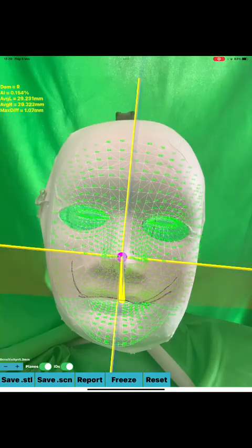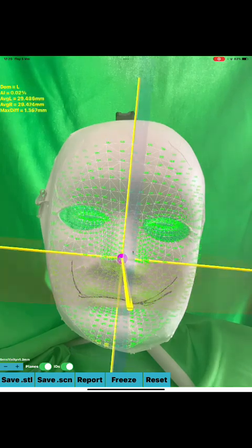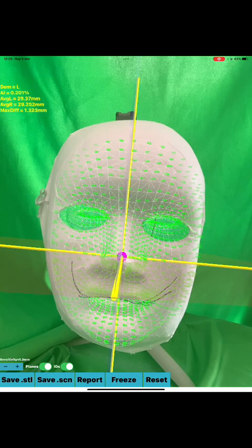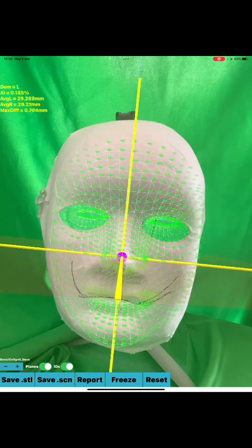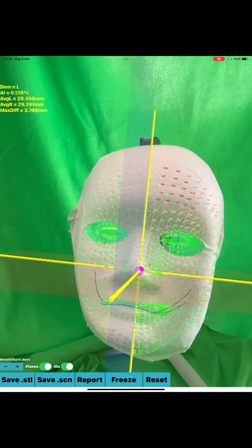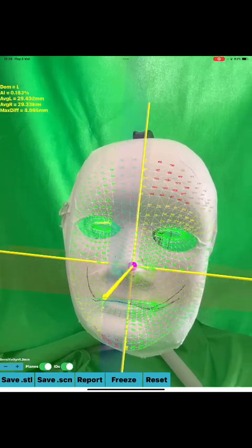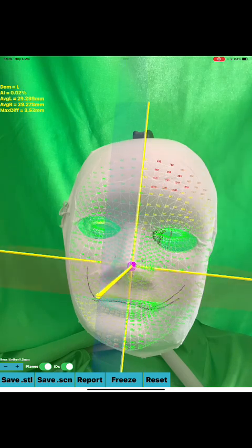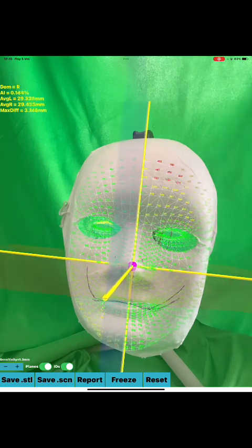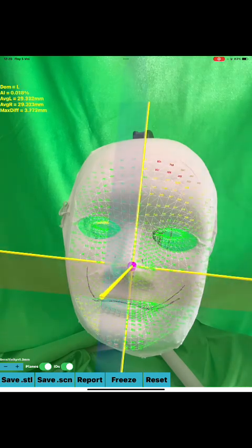The max sensitivity button by default turns points with more than 1 mm difference in distances from the mid-sagittal blue plane for each bilateral pair of anthropometric points from green to yellow, and over 2 mm to red, respectively. By pressing the plus or minus button, the threshold from 1 mm is changed to the desired value of sensitivity. For example, by pressing the plus button, more value is added over 1 mm, thus less sensitivity is selected.